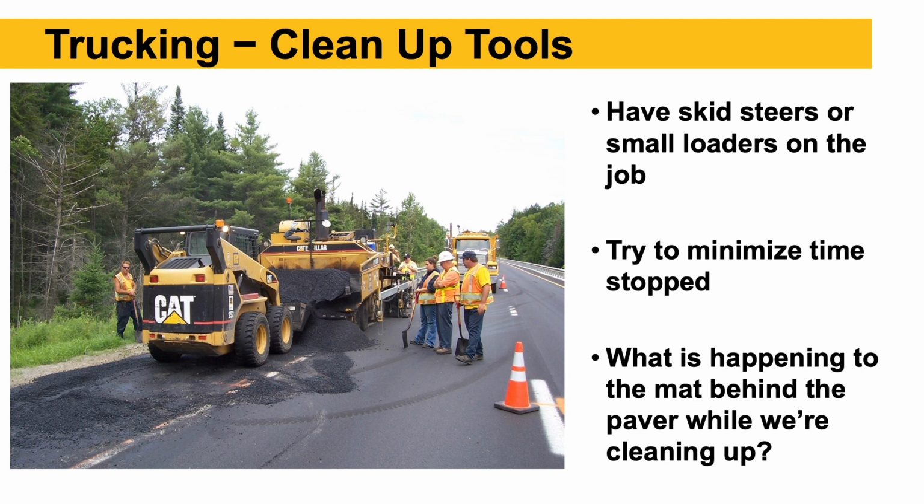Here they're cleaning up now, so that truck rolled away from the paver, dumped the load on the road. Thank goodness they had a skid steer on the job instead of having to shovel it all. So they're cleaning up that mix now, but what's happening? Well, that paver's sitting there and they're cleaning up all this mix. That mix behind the paver's getting cold, the screed's settling into the mat. We're going to end up with a bump there for sure.